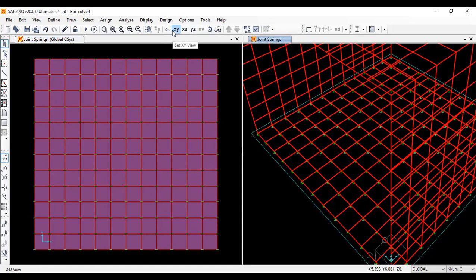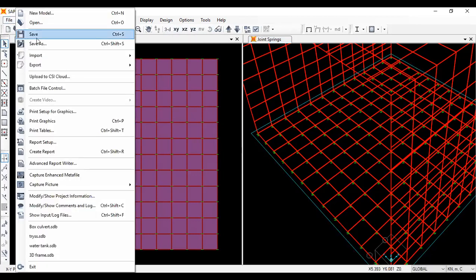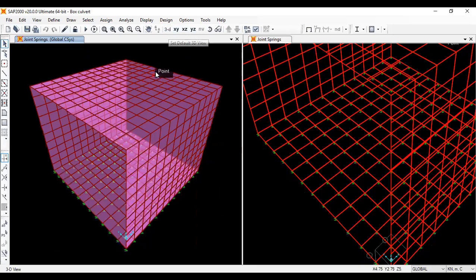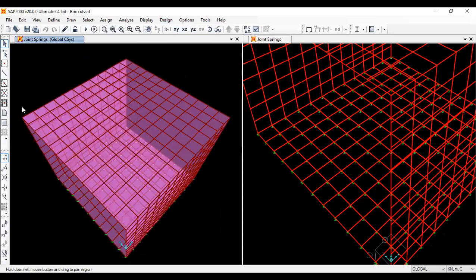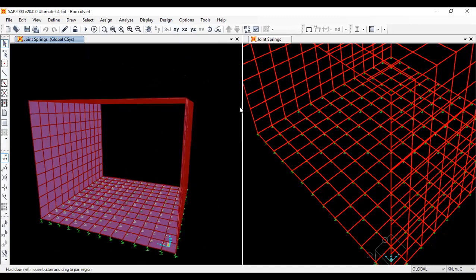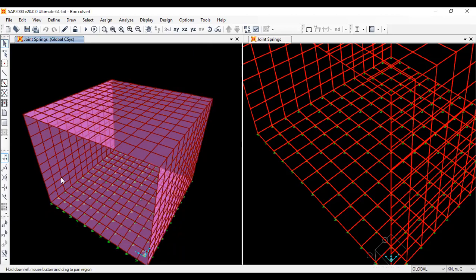and you can save it, Control S, or else you can save it from here. Again, think about the structure. Now we have applied the restraints as well. So any kind of loading, and if you need to apply loading due to traction, right, you can apply this on any line, in the horizontal direction or the road direction, right? But fundamentally the structure is not stable in the horizontal direction because we did not restrain anything.